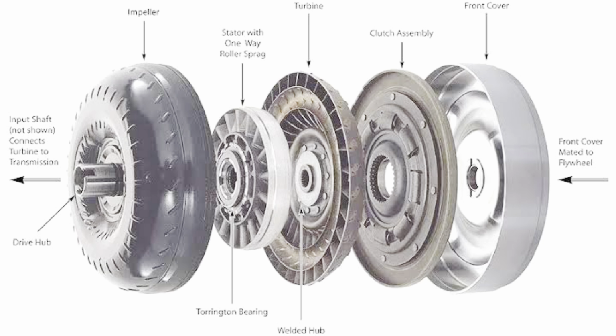Torque converter. On automatic transmissions, the torque converter takes the place of the clutch found on standard shift vehicles. It is there to allow the engine to continue running when the vehicle comes to a stop. The principle behind a torque converter is like taking a fan that is plugged into the wall and blowing air into another fan which is unplugged. If you grab the blade on the unplugged fan, you are able to hold it from turning, but as soon as you let go, it will begin to speed up until it comes close to the speed of the powered fan.